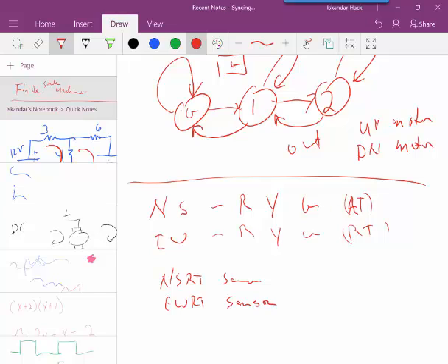What these sensors are is little plates underneath the road that, if a car is in the lane to turn right, will close the switch and tell our microcontroller that somebody wants to turn right, so on the next cycle it goes through a right turn sequence. If there's no car in the right turn lane, then ignore it.